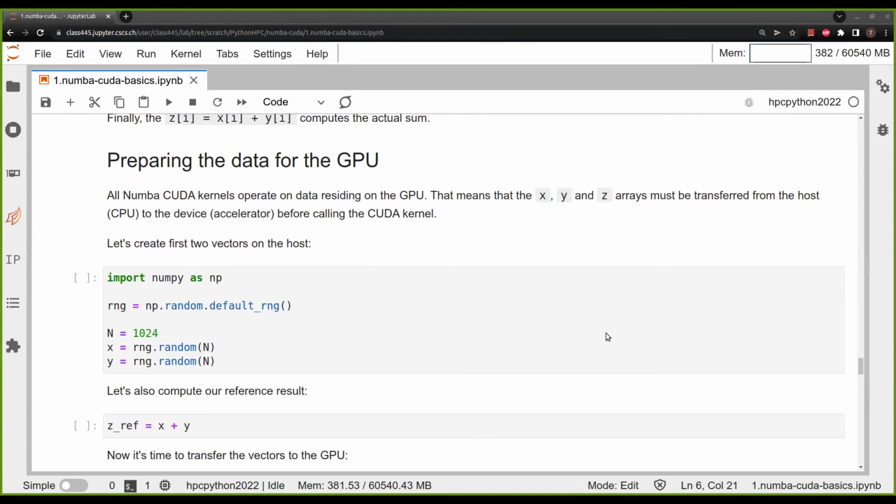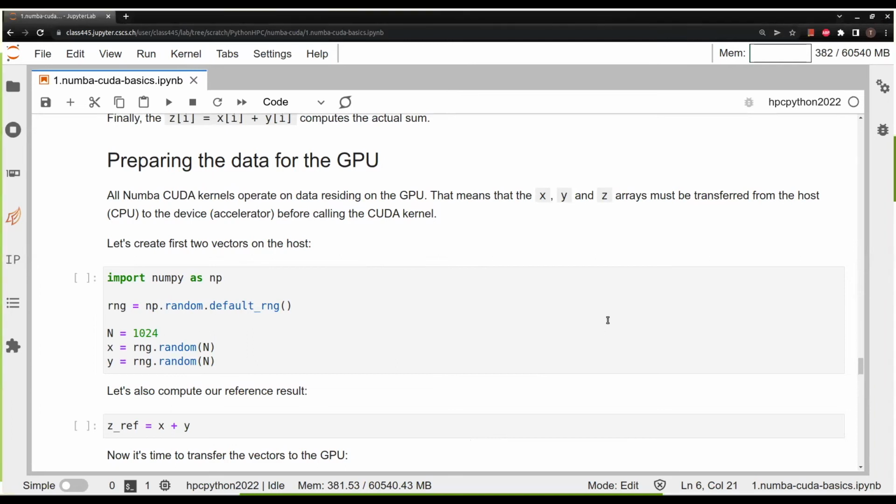Could multiple warps run at the same time, or only one warp running while all the rest of the threads wait? Multiple warps from different thread blocks can run at the same time, but the threads of a single warp must run the same instruction, all of them.